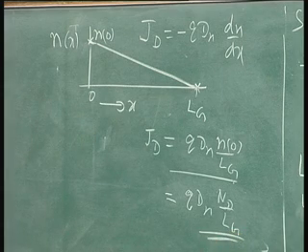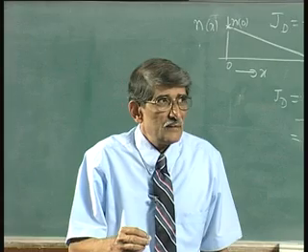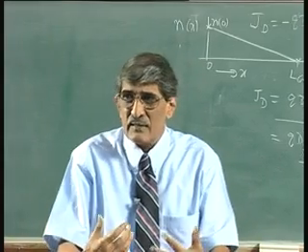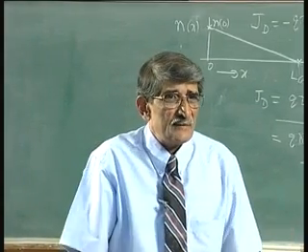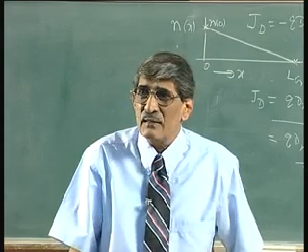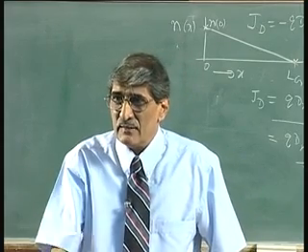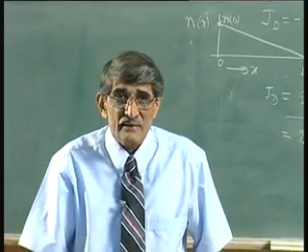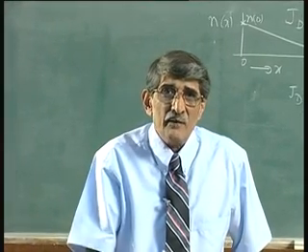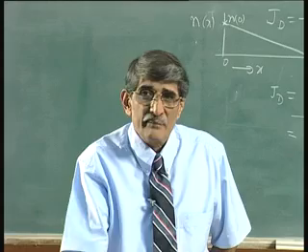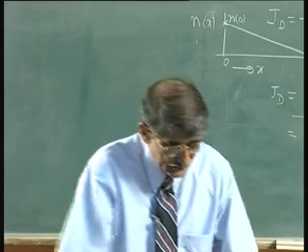So, what we are telling is there is some amount of current density giving rise to current at threshold. In fact, people talk of threshold as 5 microamperes: when the drain current drops down to 5 microamperes, that is the threshold. That is one way of identifying it. Now, from 5 microamperes, how will the current fall if we go below the Vtn? That is what we are trying to see.